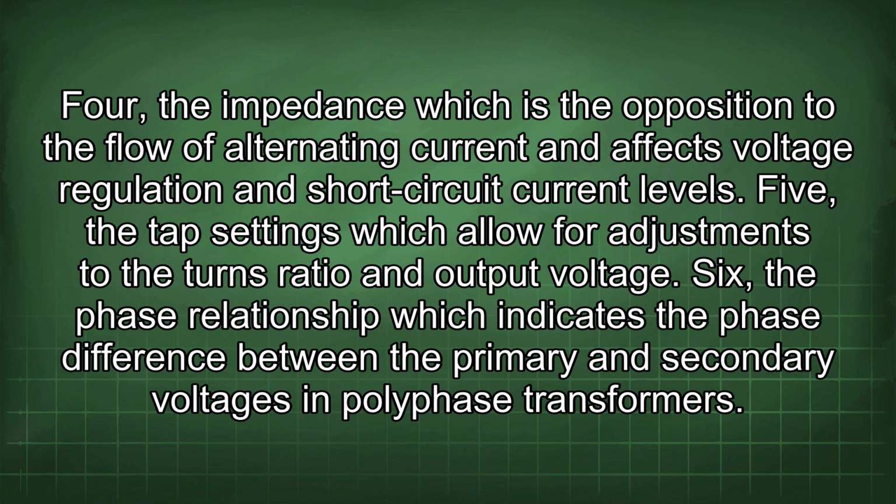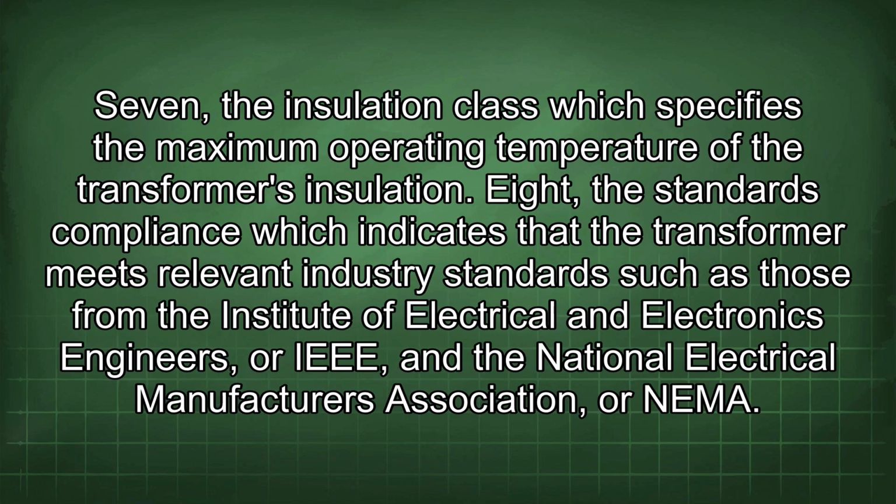5. The tap settings, which allow for adjustments to the turns ratio and output voltage. 6. The phase relationship, which indicates the phase difference between the primary and secondary voltages in polyphase transformers. 7. The insulation class, which specifies the maximum operating temperature of the transformer's insulation. 8. The standards compliance, which indicates that the transformer meets relevant industry standards such as those from the Institute of